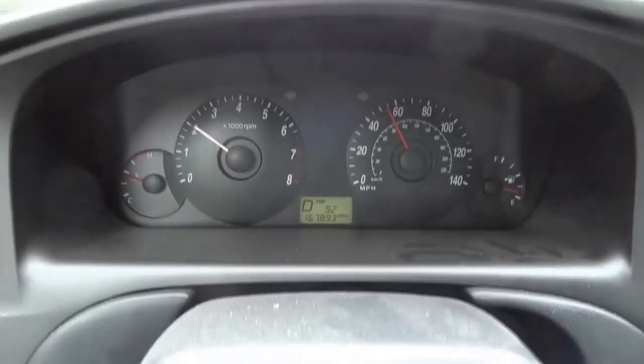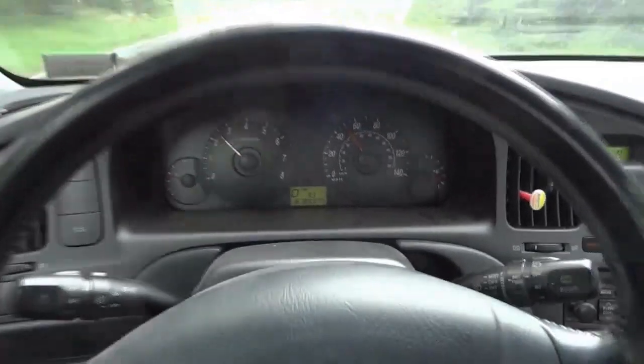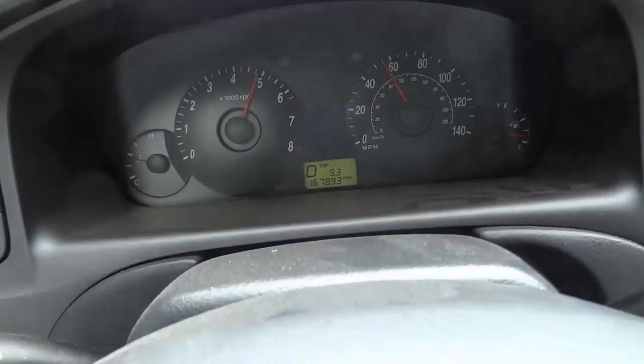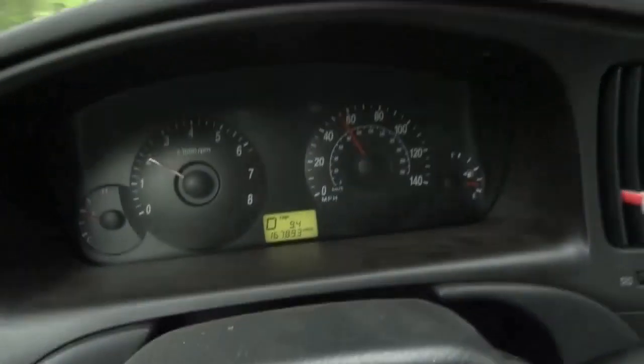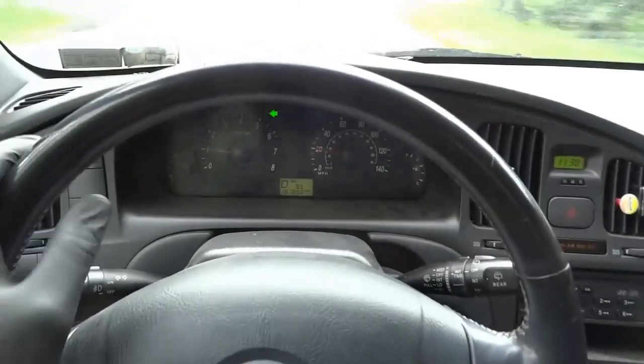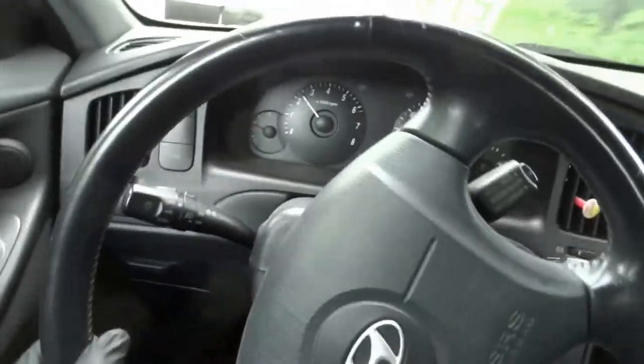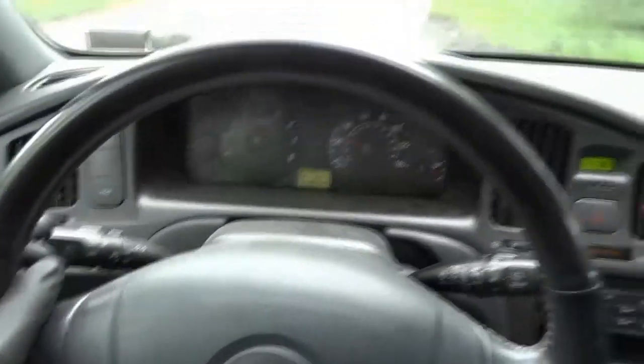Guess what? The vehicle is now going over 25 miles an hour. Remember, before, this vehicle could not go over 25 miles an hour. Well, this vehicle is fixed. Okay? So let's give it gas a little more. So right there, we went all the way up to 60 miles an hour. So this is fixed. The problem on this Hyundai was a clogged exhaust. The exhaust system was clogged. So that's why this vehicle could not go over 25 miles an hour.